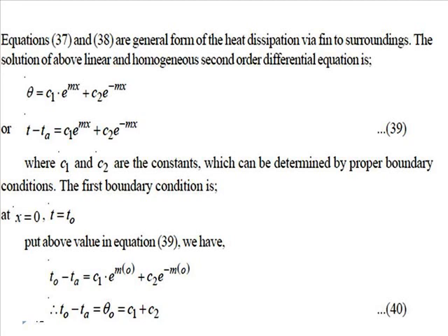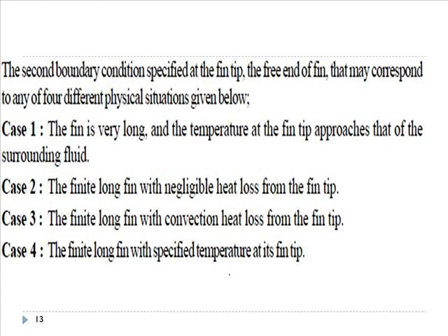This is the one common boundary condition available for a rectangular fin: at x equals 0, the temperature equals the base temperature. Now the second boundary condition depends upon the type of application. If we consider case 1, then the fin is very long, or infinitely long, and the temperature at the fin tip approaches that of the surrounding temperature.